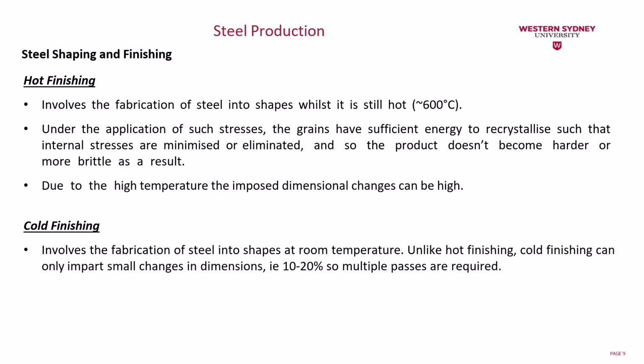Cold finishing involves the fabrication of the steel into shapes at room temperature. Well, actually, it's not going to be room temperature. Sometimes something like 100 or 150 degrees is considered cold finishing. So unlike hot finishing, cold finishing can only impart small changes in dimensions, for example about 10 to 20%, so multiple passes are going to be required in that case.